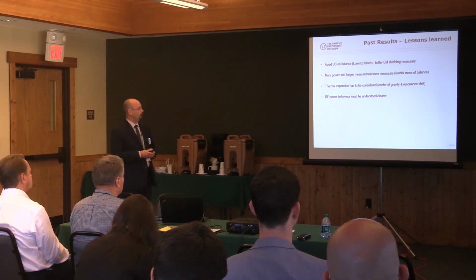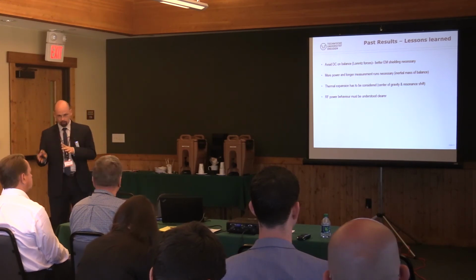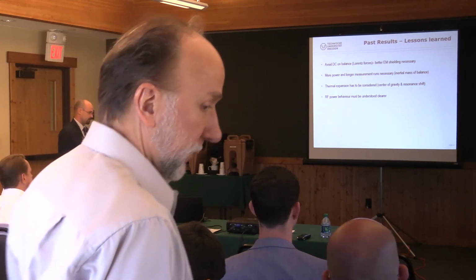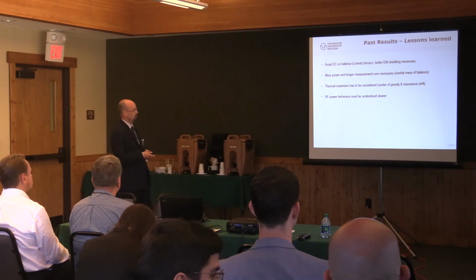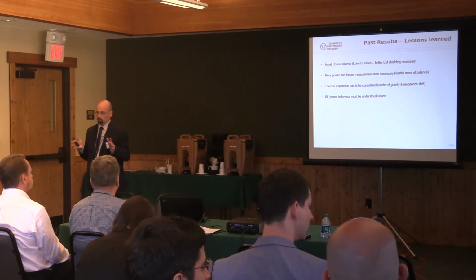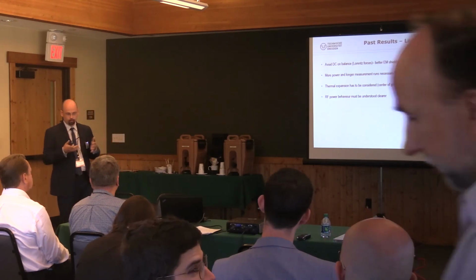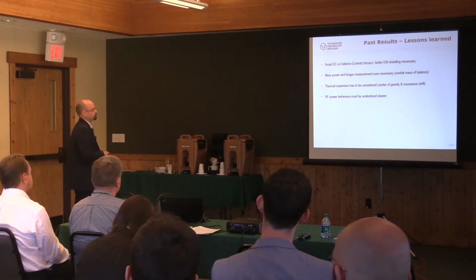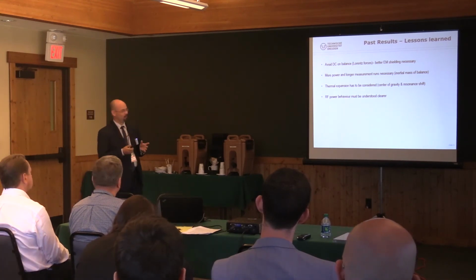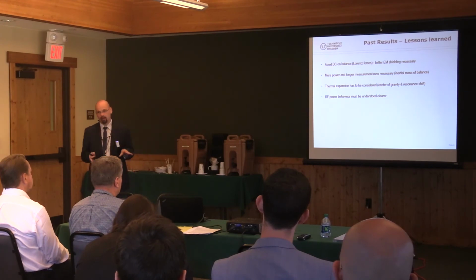We have to be aware of the thermal expansion of a cavity if there's enough power inside of the cavity, because the center of gravity shifts, and so we could get some false results. And we have to be aware of a resonance shift of a frequency, so we have to use a tracker, which probably, yes, we have to stay at our principle of using a tracker. Well, and perhaps we have to understand better our RF behavior inside the cavity.